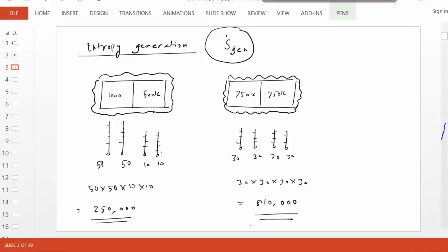And how can it happen? Entropy is not coming through mass. Entropy is not coming through heat. There is no heating. This is insulated. So entropy must be generated. So this is a process where a temperature difference is being destroyed, and we see that entropy increases as a result. As a matter of fact, it can be shown that in all gradient destroying phenomena, entropy increases. Entropy is generated because of entropy increase if the system is closed, if there is no other way for entropy to change.